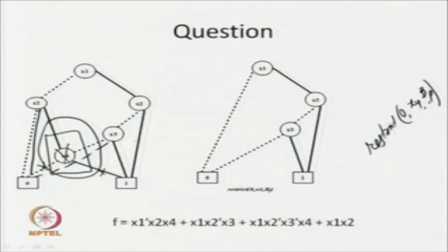Now, we are going to look for whether reduction is possible or not. You will find that this x2 is a redundant node, we are having a redundant test. So, we can remove this particular x2 also. This is the application of the reduction algorithm. So, eventually we are getting this particular BDD. If x1 is 0, then it goes to 0; if x1 is equal to 1, then we take a decision on x2, then 0 and 1, then we take a decision on x3. So, this is the ROBDD for restrict 0 x4 bf.